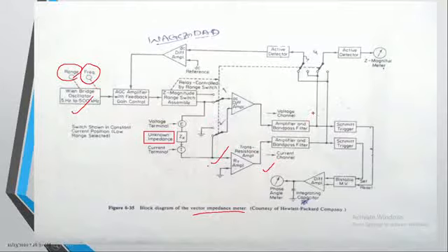And for this unknown component, from the vector impedance meter, we are interested in calculating the magnitude. So this meter is acting as a magnitude meter, and this meter is acting as a phase meter.